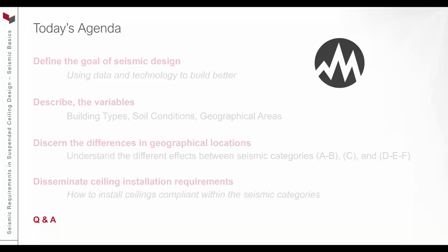And last question here. Having a 3/4 inch space at a 7/8 inch wall mold is quite unforgiving. Have you ever encountered a problem with this type of installation? The installers have come to cut those cross T's really clean, and so the 7/8 or the 3/4 inch gap only allows for an 1/8 inch. USG has pretty much developed a perimeter wall angle that's a little wider, so it's 1 1/8 wide.